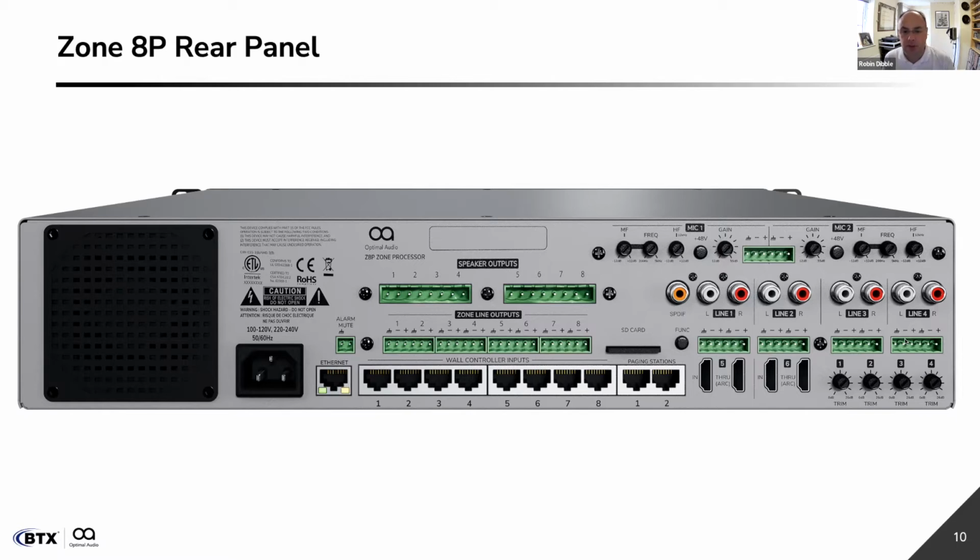So at the top, 2 microphone inputs with an analog preset EQ on the back. Then we have stereo inputs 1, 2, 3, and 4. The first one is available as balanced, unbalanced, or digital SPDIF connection. The others as balanced or unbalanced, straightforward analog audio. 5 and 6 can be balanced audio, or they can be audio stripped through from an HDMI stream. So it'll take audio off, then you pass the image through to a subsequent screen.